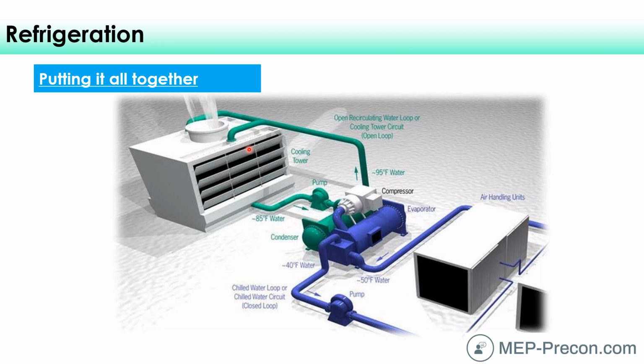Well, this is going to cool down that water, and to do that better and more rapidly, we'll have a fan at the top here. We're going to force air across all of that surface area of that water to force evaporation at a higher rate. And as we do that, we're going to remove BTUs more efficiently, and that water then correspondingly drops down to this sump down here, kind of like a big bathtub of water. It's kind of a holding reservoir, and it's going to be colder than the temperature up here because we've removed those BTUs. What happens to those BTUs? Well, the BTUs leave out of the top here as a very warm, moist vapor.